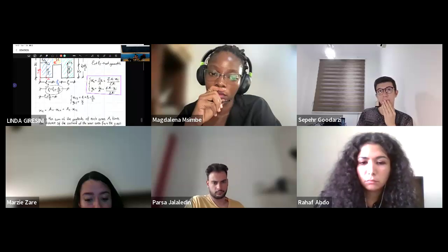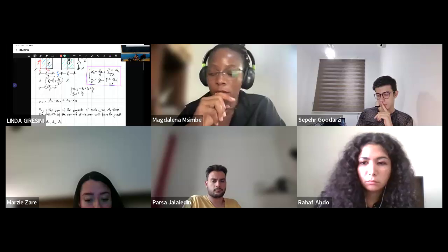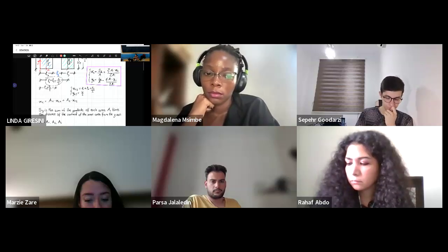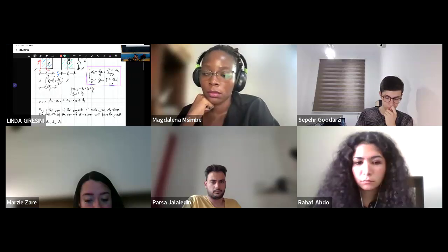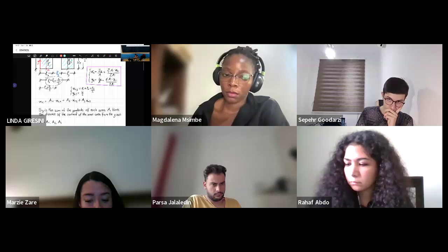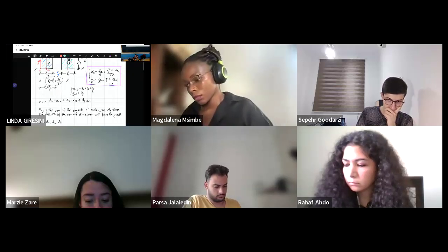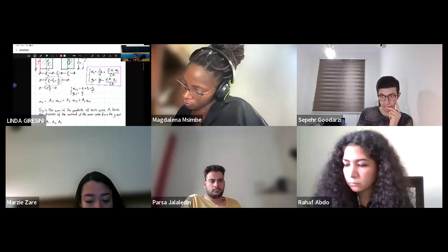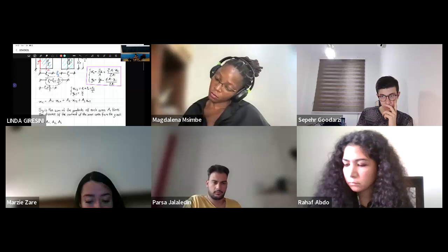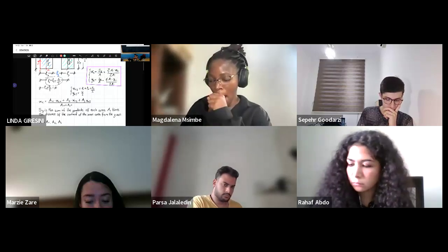So let's come back to XC then. It's important that you all understand. So if you have some doubts, just ask. Then we have plus A3 times XC3. This is the sum of the products of each area Ai, A1 times XC1 plus A2 times XC2 plus A3 times XC3. So indeed, it is the sum of the products. And this divided by what? A1 plus A2 plus A3.